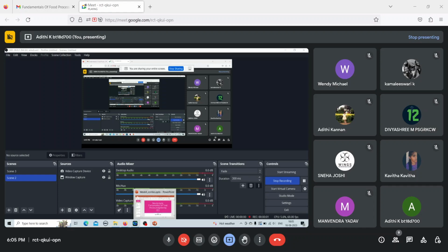We already know F and we calculated L, so we can substitute back in the total mass balance equation to calculate V. So substituting back in the total mass balance equation, 120 equals 41.05 plus V. So V is equal to 78.95 kg per hour. The answer given here is option C.